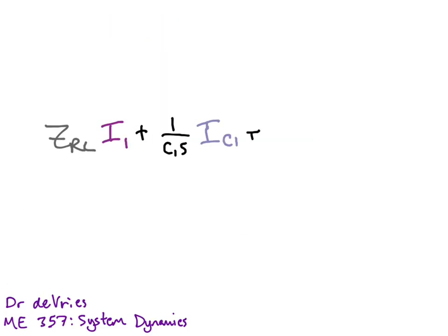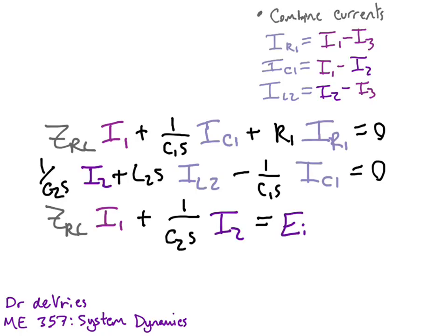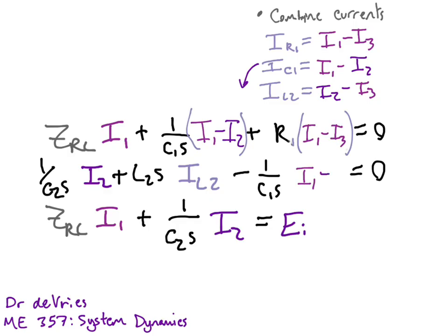And here, what's going on is, let's go here. So here we have the currents we were given, we have our equations that we had before, and now what we can do is replace those little currents that are named after nodes with just I1, I2, and I3. So we replace them all, and that way we have our equations just in terms of those three current variables.